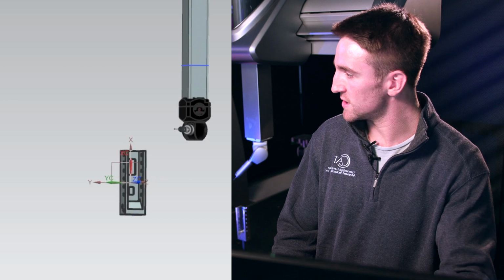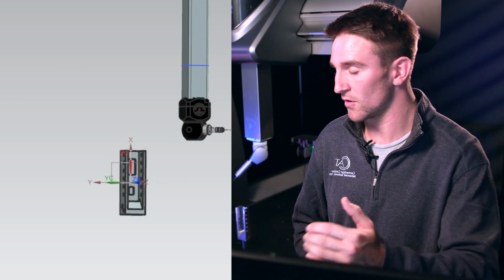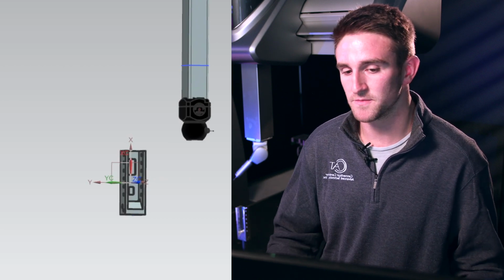So we can see how that resequence path saved us a lot of time from having to organize the order and letting NX make those optimizations. Yep. All of this has been done with applying PMI at the design site. So my job as a programmer, I receive the file, a CAD file that has PMI properly applied. Yep. I import it and follow the steps that we've been talking about.